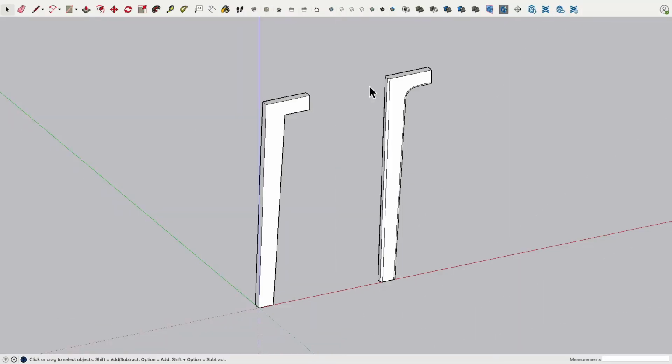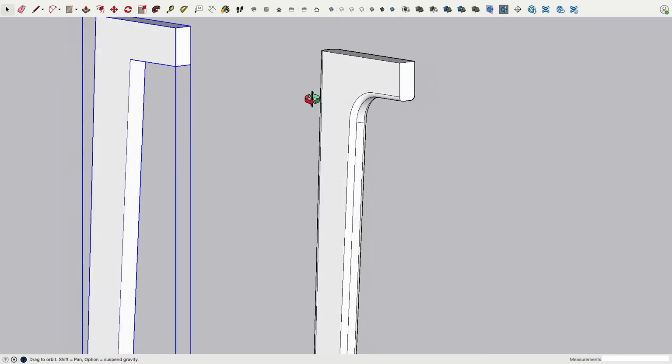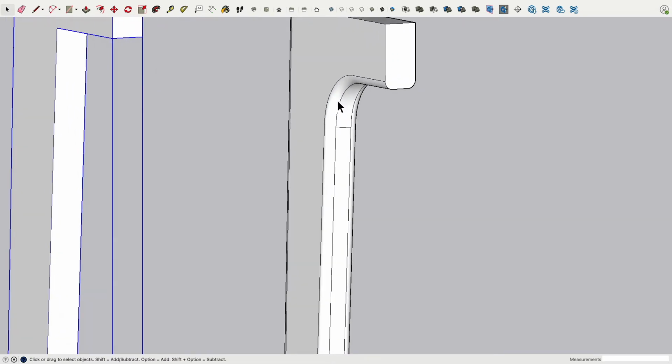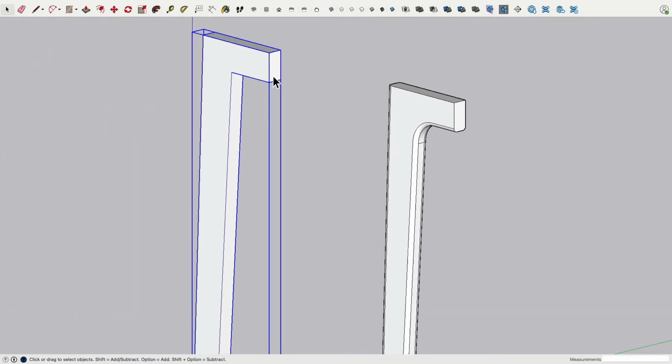I'm back with a very quick tutorial, I promise. Okay, so the topic of this exercise: we will turn this leg into this leg. Particularly, what I will show you is how we can remove certain elements, for example, these rounded edges, these rounded areas, and then rebuild the edges and faces cleanly in SketchUp.